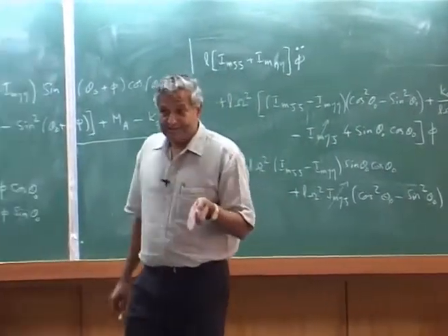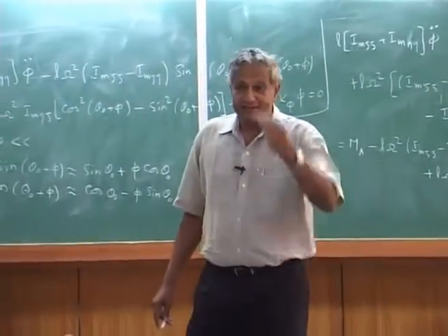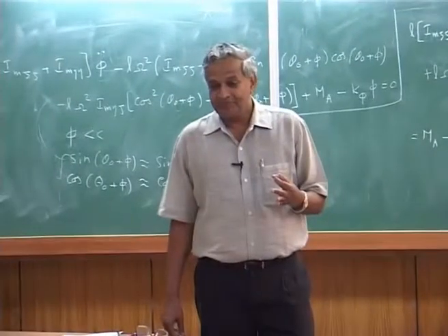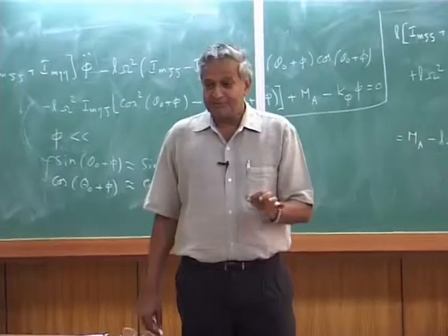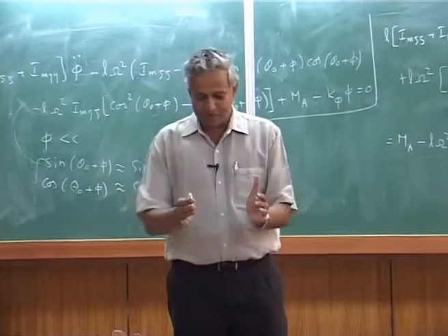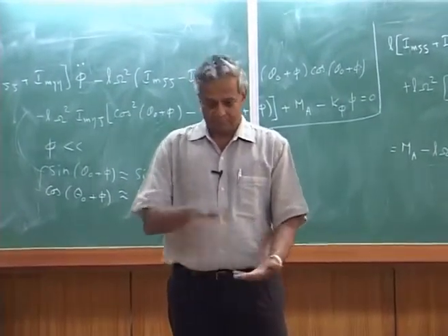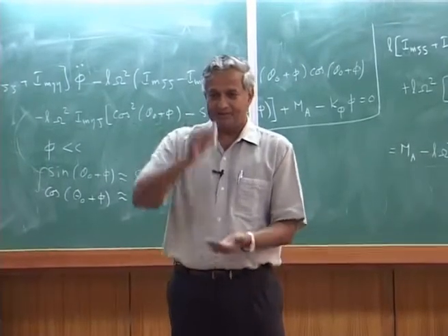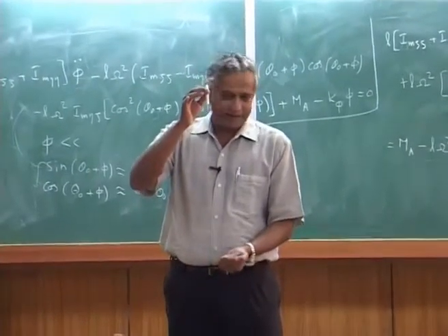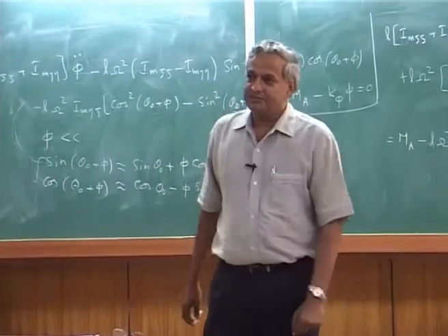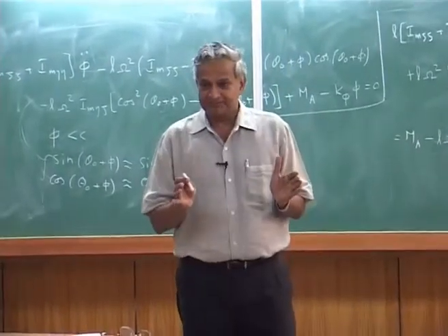That is why in the industry they calculate the control system stiffness. You will have the swash plate, and then there is a hydraulic jack below the swash plate, above the control rods. You calculate the stiffness of the entire unit.